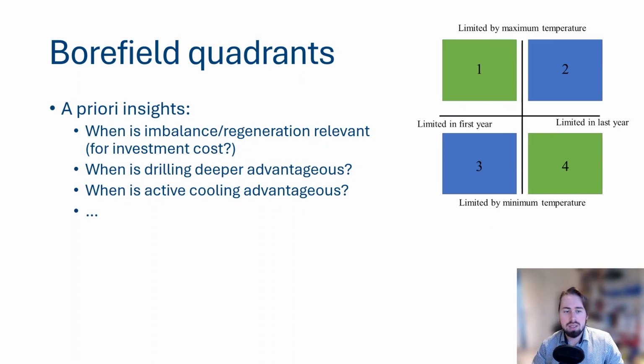Another question is, when is drilling deeper or making your Borefield deeper advantageous? Now in Belgium we have a regulation where if we do not drill below a certain depth, typically 150 meters, then we do not have to file for a permit. So people mostly stick to that threshold. But from a thermodynamic or HVAC point of view, sometimes it's better to drill a little bit deeper.